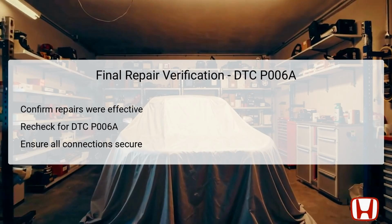Additionally, take the time to recheck all electrical connections and wiring for the MAF and IAT sensor 1. Poor connections can lead to intermittent issues that may mask underlying problems. If everything appears satisfactory, take the vehicle for a test drive to observe its performance in real-world conditions. Confirming the integrity of repairs not only solidifies the current fix, but is a critical step toward preventing future issues.